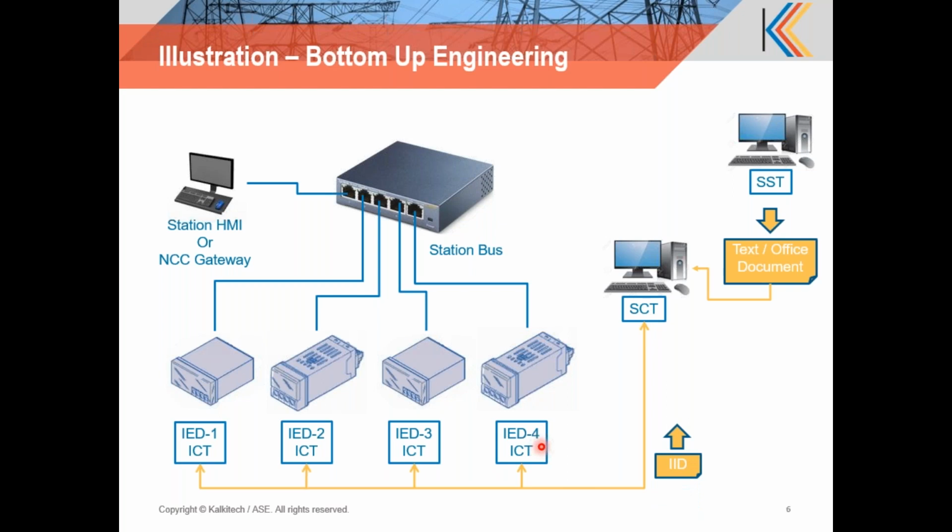Finally, as a form of paying lip service to the standard, the user will export an IID file from the ICT tools, which is basically an instantiated IED description. Now, an IID file is different from an ICD file in the sense that it contains not just a template of the functionality that is available, but it contains all the engineering that has already gone into the device. That is, it contains the data sets, the reports, the GUIs, the addressing information, everything that has gone into the configuration is available in this instantiated IED description file.